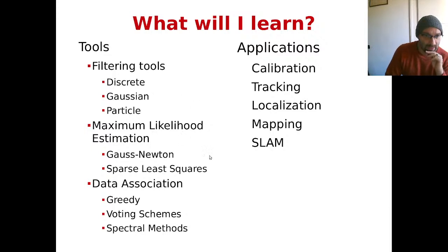In the second part of the course, we focused on an offline estimate, or a batch estimate, of the state of the dynamic system, and then we introduced basically Gauss-Newton and its variants, and we unveiled the structure of the problem and devised a methodology that allows us to approach even large batch estimation problems. And in this context we also introduced new techniques for data association that relax the assumption of having an initial guess, for instance RANSAC, that falls into the voting schemes. I did not talk about spectral methods. My pity means that I will not ask about spectral methods.